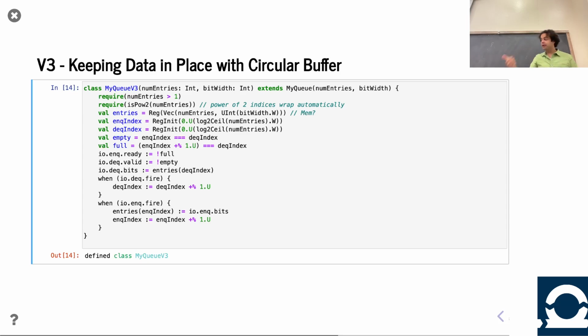You can imagine where we started: a single entry queue, then a shift register with a priority encoder, and now a circular buffer. So you can see our microarchitecture keeps changing, but the big picture is not changing. The big picture of implementing a queue, what the interface looks like, is not changing. We're able to reuse those test benches. The rest of our teammates working on other projects, part of a larger design, can still interface with our module, still push us through the tools, and still see things. That's kind of the point: there isn't a gaping hole in the design until this is done and supposed to be perfect. They have something, and we keep improving it so that hopefully it can be smaller, more efficient, you name it. That's an agile incremental process at work.